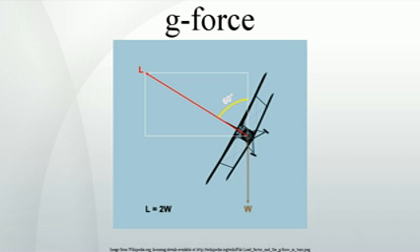Short-duration shock and jerk. Short-term shocks may be caused by impacts, drops, earthquake, or explosion. Shock is a short-term transient excitation and is often measured as an acceleration. Very short-duration shocks of 100 G have been survivable in racing car crashes. Jerk is the rate of change of acceleration. In SI units, jerk is expressed as m/s³.